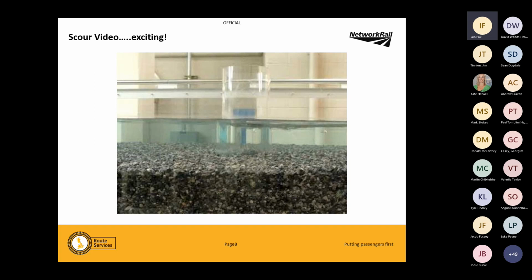And we've also got some little air bubbles. This is called air entrainment, which is another telltale sign. When you start to get bubbles downstream, you know you've got very turbulent flow. On this one, you'll also see some bits of material start to flow along the base of the bed. If you watch, you'll see some little bits and pieces just flowing around. We'll go again, up to 50 litres a second. So we've now got quite a lot of air entrainment. We've also got some particles starting to move.